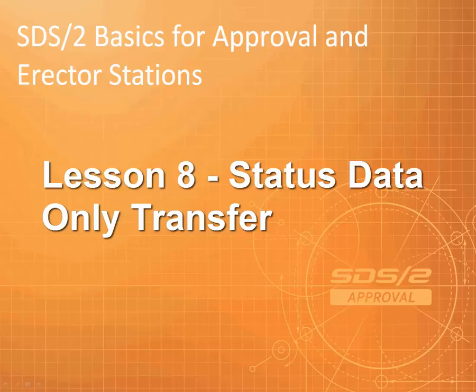viewer station. The Status Transfer Only can be launched from the main menu or from the model. It is more advantageous to run the tool from the modeling for export due to the ability to visibly select the items from the model instead of a list, plus the added benefit of using a masking tool to hide what you do not want to select. The Status Transfer Only will export member status and custom property information as well as material, bolt, weld data through